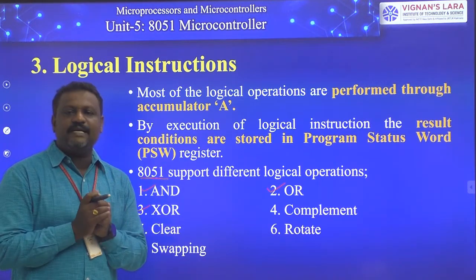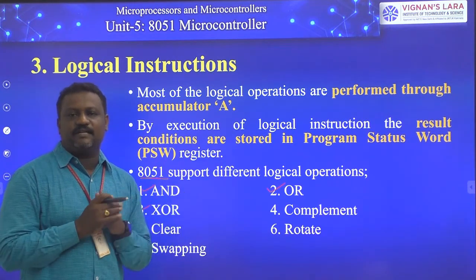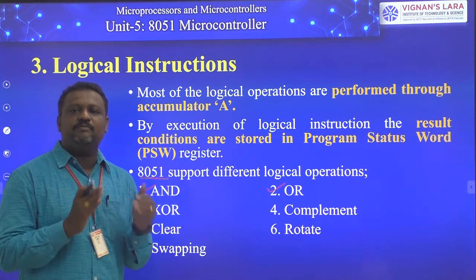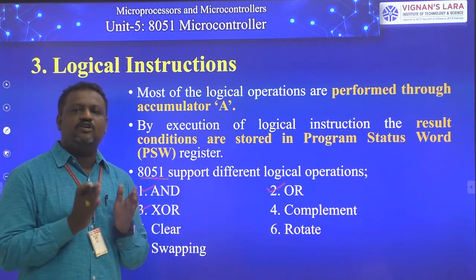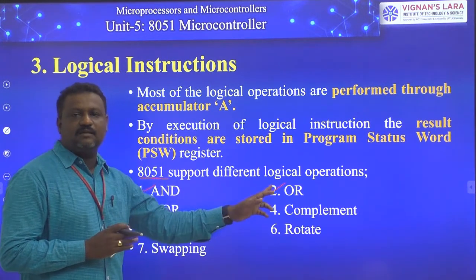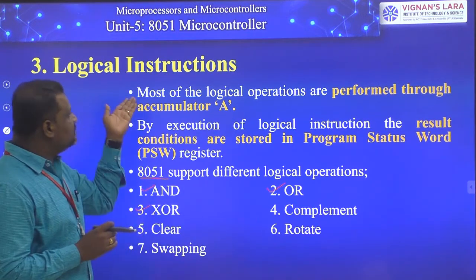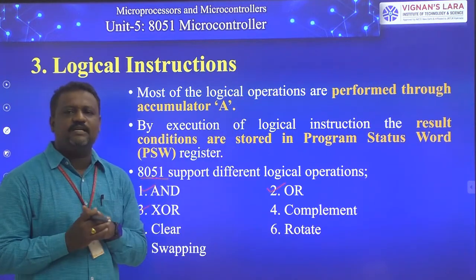Out of those 2 data, one may be provided by the accumulator register. I won't say that 100% of the time the accumulator provides one of the operands, but in maximum cases the accumulator participates in these logical operations. So, most logical operations are performed through the accumulator itself.